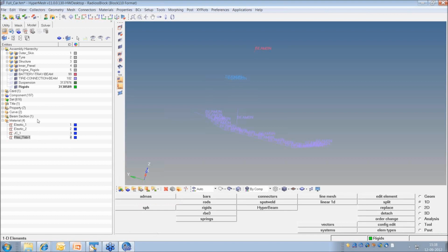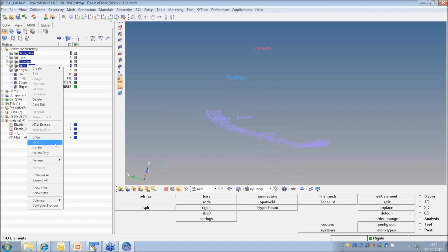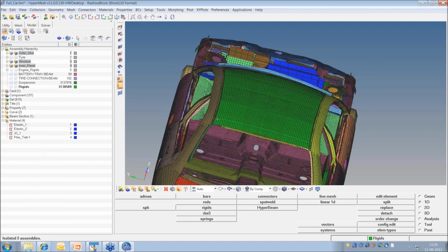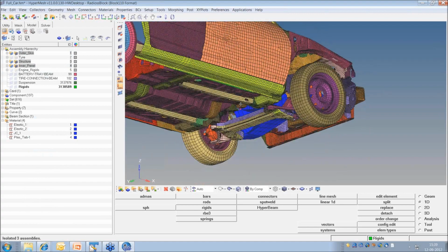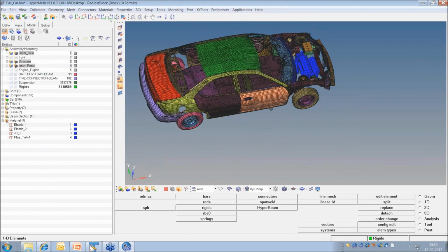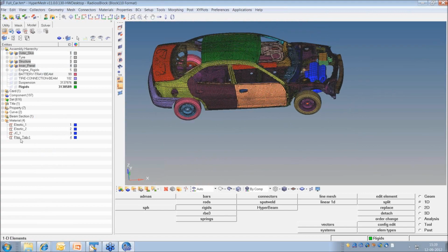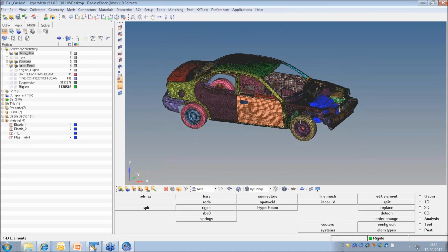Now it is my job to assign the materials to the components. So I'll again go by the same method as I did for the properties. First, my idea is that for all of these, say outer, structure and inner, I will assign this mat law 36, which is a very comprehensive material.